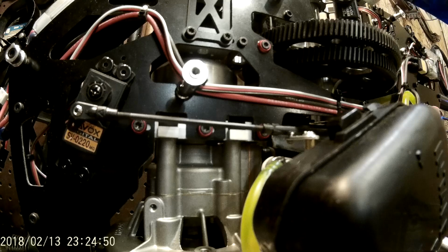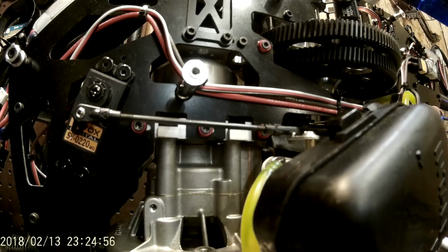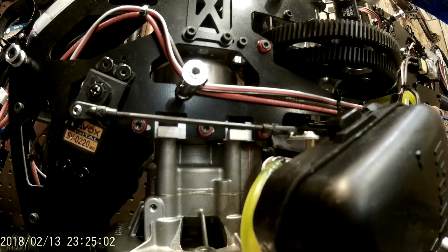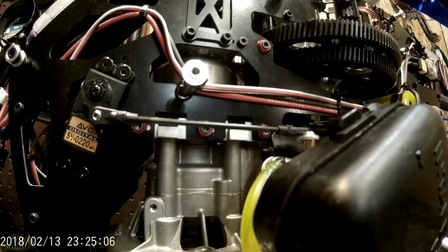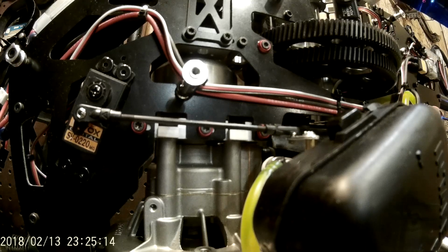Right here, this is the bottom of the collective pitch range. This is the middle of the collective pitch range. Right there, we're at mid-stick. Now as I advance, I'm going to move the throttle starting at the bottom. We're going through middle collective right there, and now we're at the top end of the collective range. You can see how much faster the throttle moves in the top end of that collective range versus at mid-stick. Right there, we're at mid-stick again.